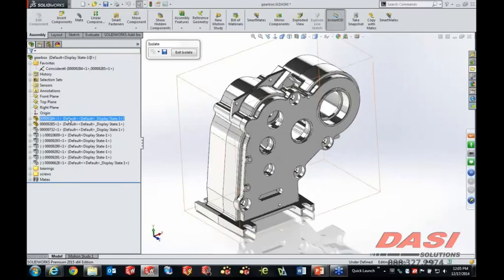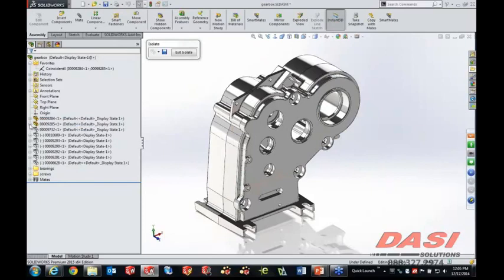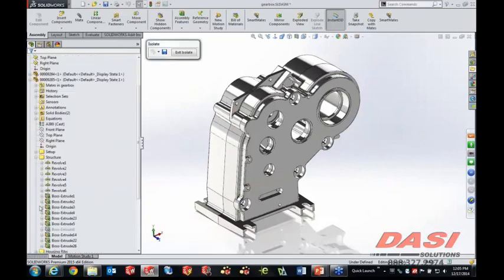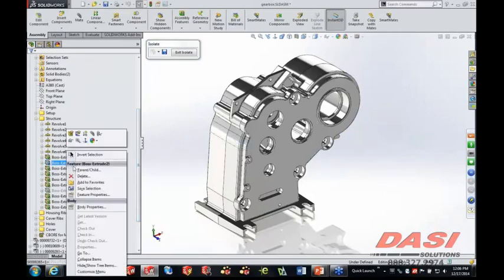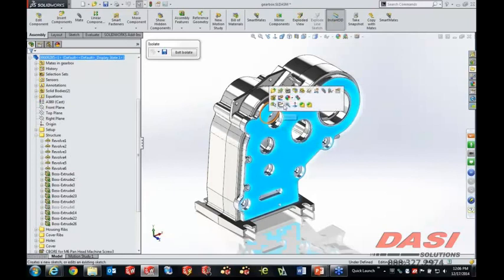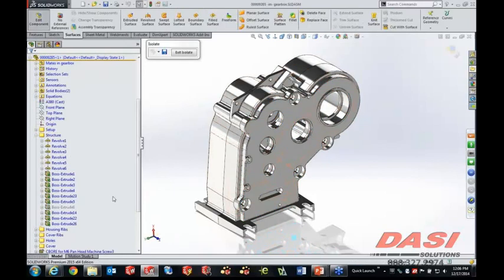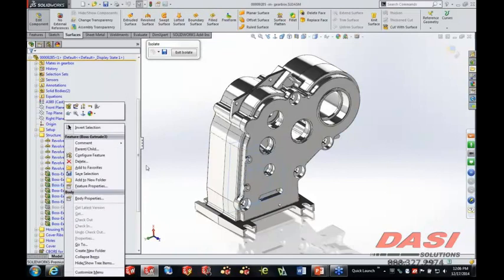Now, the Feature Manager, anybody that's used SolidWorks or really any other CAD system that's parametric in nature for more than a short time, you've already realized that there are parent-child relationships set up within the product. Now, these parent-child relationships are something that you can visualize by simply going to any feature in the Feature Manager and doing a right-click, and that option's always giving you this thing that's called List External References. Well, now what you can do is just simply hover your cursor over top of one of those. So if I happen to be editing a part within this assembly, now we're focusing on this feature tree, if I right-click on any of that, List External References is a tool that we can go ahead and show.